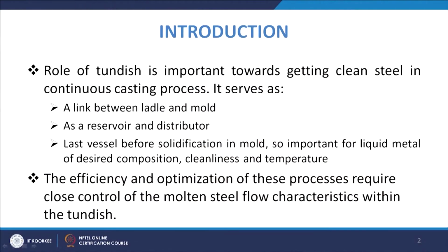Otherwise, once it leaves into the mold, if some external entity is there inside the liquid melt, it does not have any further chance to be skimmed off, although there may be somewhat. This is the last vessel before the metal goes into the mold for solidification. So, you need to have considerations for the liquid metal to have the desired composition when it enters the mold, and to be free from any kind of defect, like it is clean, there is no